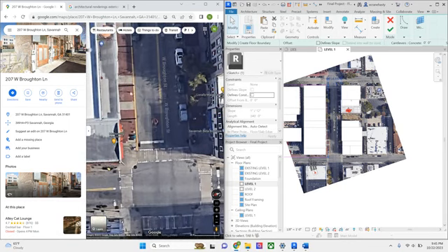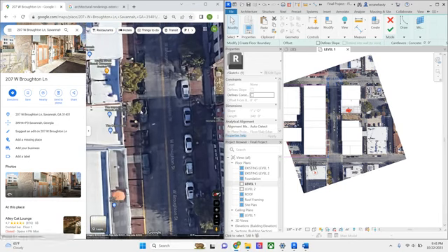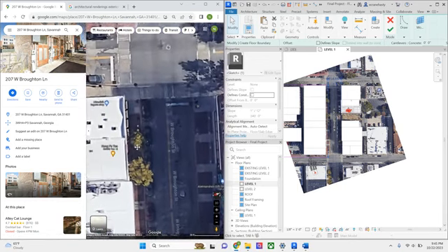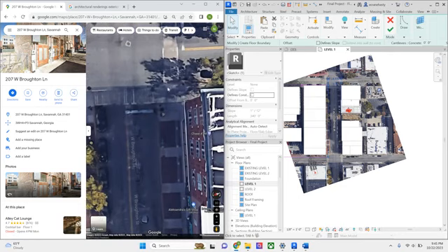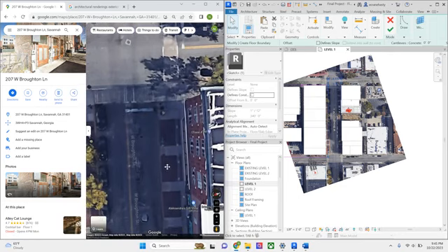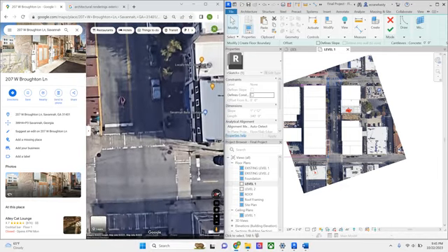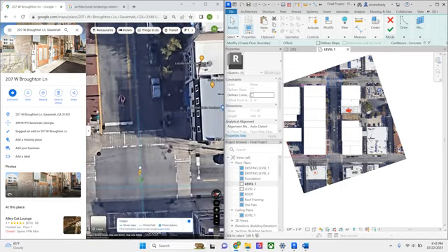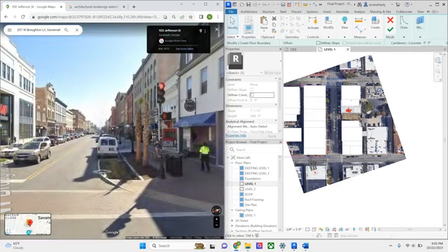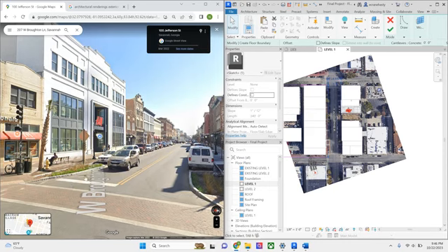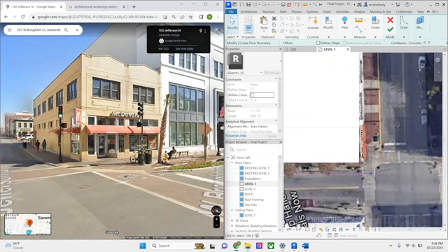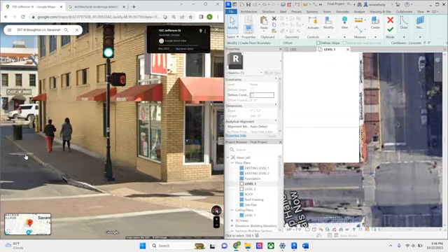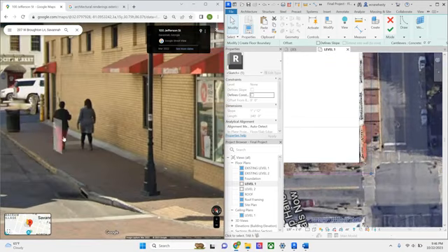It radiuses, comes down, becomes parallel parking, and then rounds back. And then over here, we have it coming down. But when I come down here, notice that the streetscape looks different. They've created these little inlets. So I'd really like to start modeling what the inlets are. And I am just going to reference them literally by estimating how big they are from these people.